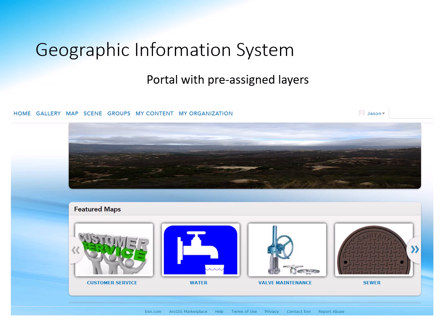The other thing I didn't mention is that with GIS, there's definitely layers to that system. So you don't have to look at everything that's out there. You can isolate it, or filter it, to what it is you're really trying to see. Are you just trying to see pressurized mains? Are you just trying to see abandoned mains? Are you trying to see certain pressure zones? Are you just looking for services, hydrants, etc.? The nice thing about GIS is that you can really fine tune it into what it is you're trying to look up.